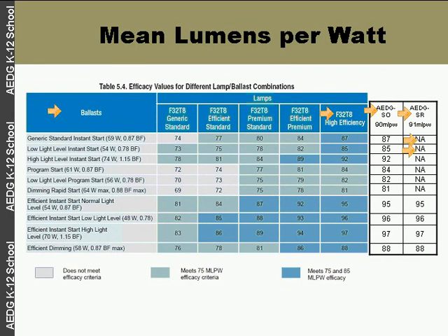And the difference between those two: general warehouse is large, bulky items. You might have 25-foot high racks. Fine storage might be nuts and bolts, small things that are hand-selected instead of selected with forklifts. So we need a little bit higher lighting power density in that fine storage area. And then the recommendations for the office are just the recommendations that we see from the office guide at 0.9